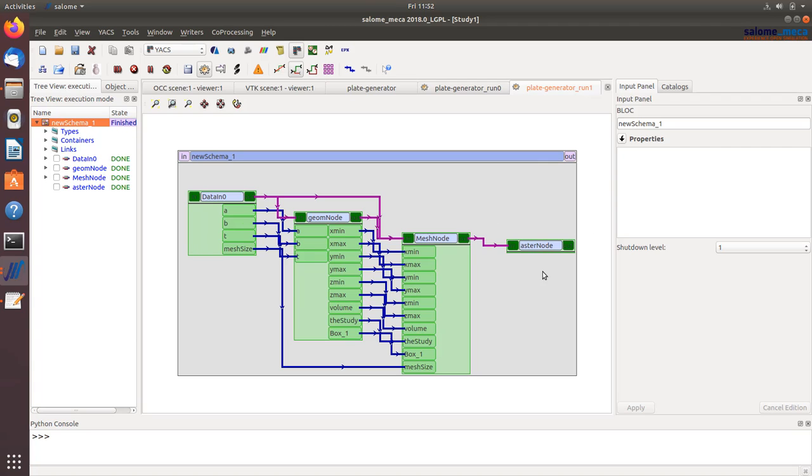And now maybe we can have a quick discussion about how you would make that parametric, because I showed you some way to insert some parameters here and to change in function of those parameters. What if I want to put some parameters for the simulation as well? Well, that would be a bit more complex, but it's doable as well. The only thing you need to know is that to modify the simulation, you need basically to rewrite the COM file.